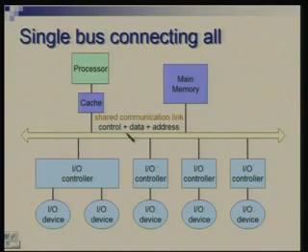So, the design of a bus is determined by how you organize these signals, what is the number of wires assigned to each, and in terms of time sequence how this information is carried. But the basic idea here is that you simply allow one set of wires to connect everything, and obviously a limitation of this would be that only one pair can be communicating on this at any time. If there are more than one pairs which need to talk to each other, the conversations have to be sequenced, but it's very convenient and cost effective.